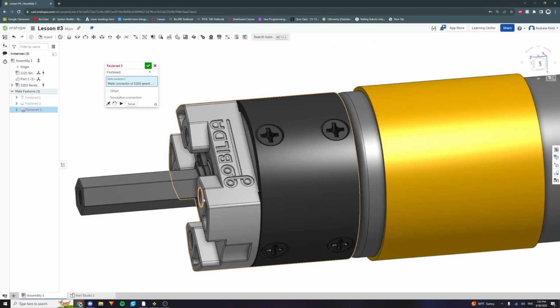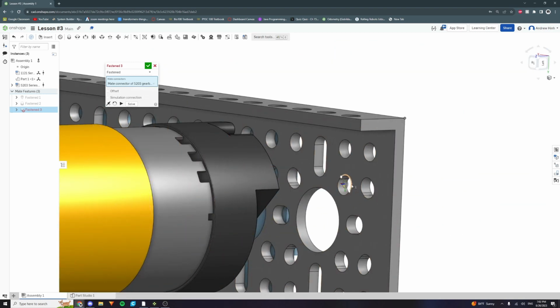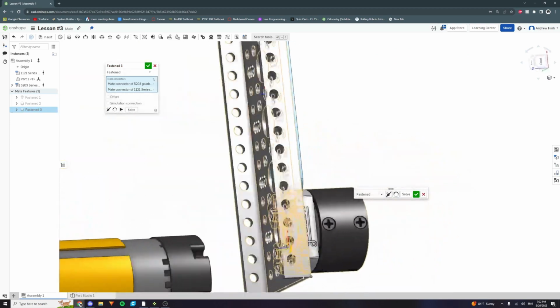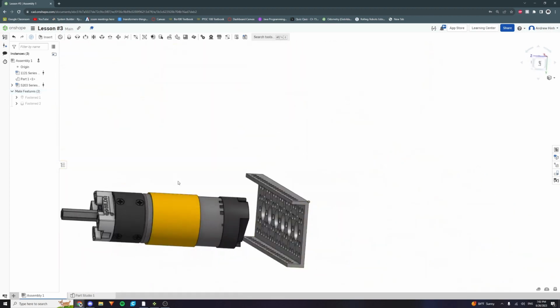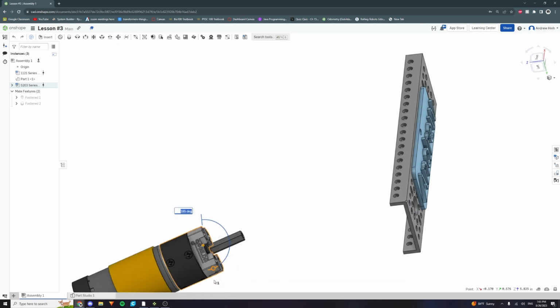let's say I want this hole here to be on this edge. So click that. As you can see, it won't fasten properly. It will go inside the U channel, which we don't want. So just make a habit of reorienting the part whenever you import it.